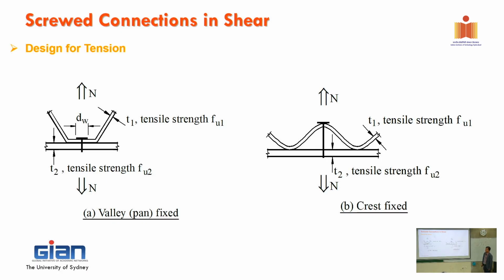Prefer the crest fixing, sir? Screw, water leaking, maybe the low water on the top. But I think in practice, normally they have the rubber washer somehow in here, right, to stop it from leaking. So that's how it works in the roofing system. But sometimes they put it on the top of the roof, not on the bottom of the roof like the other.